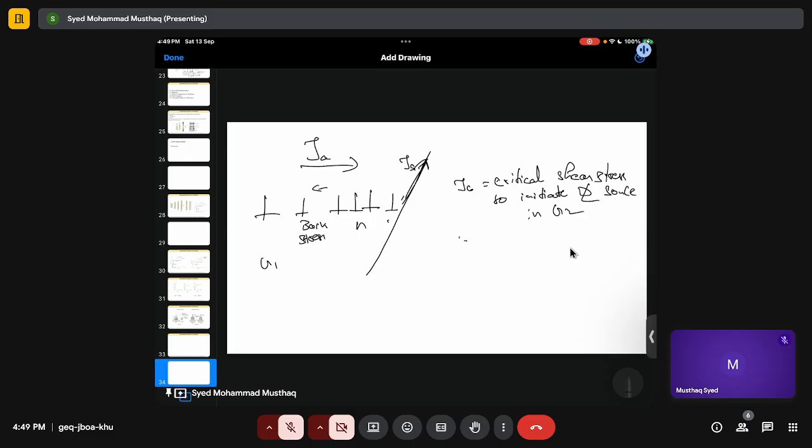Now, whenever you try to move a dislocation, there is also a lattice friction, because you need stress to move lattice planes. So what is the minimum stress to move this? Let's write it as the frictional stress, the stress coming from the lattice. So what is my critical shear stress? It will be equal to n times the resolved shear stress. If you have one dislocation, then the critical stress will be equal to the resolved shear stress that is applied. If there are n, then n times that.